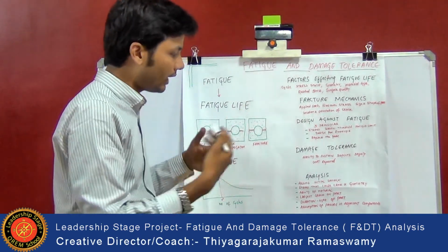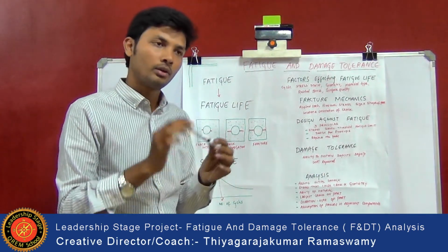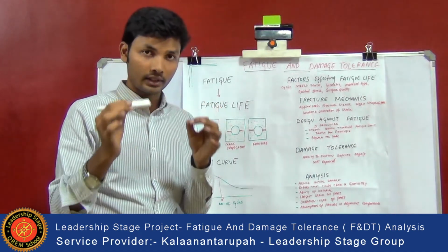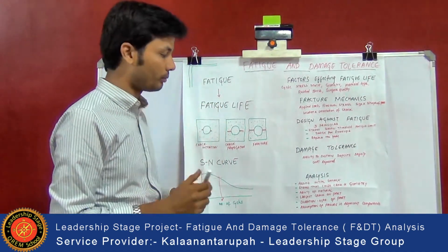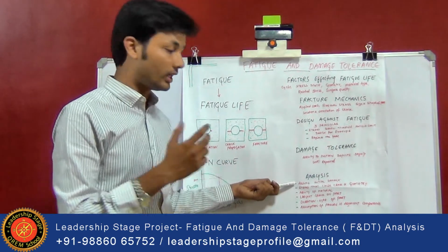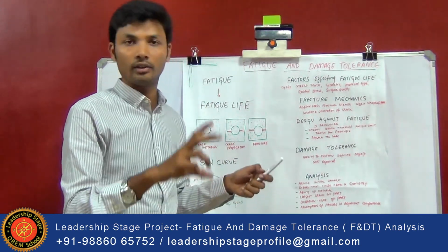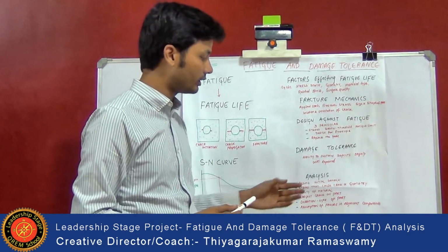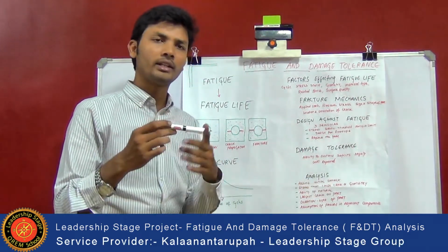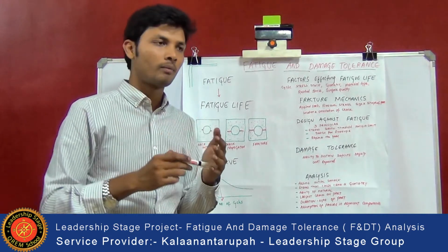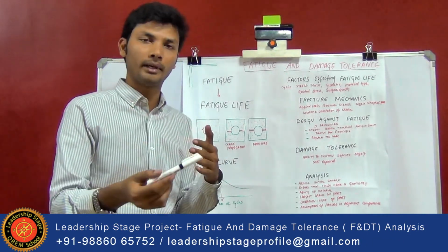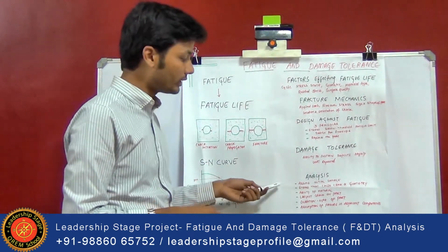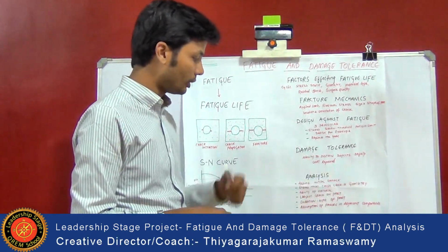But as we already know the process, to some point we can assume the initial damage, where the initial crack will start. So we need to study the whole component and the process to see where the initial damage is, so that we can study and rectify it. The second is the stress and geometry that will cause the crack. It is nothing but the stress going beyond its endurance point, or beyond its fatigue limit. If it goes beyond that, there is a chance of a crack.